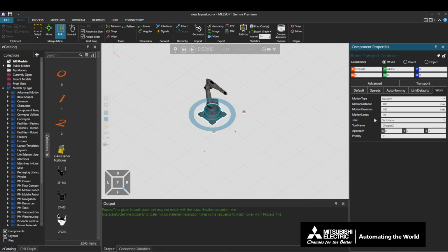Setting a keyword here requires a character string of 4 or more characters. The character string set here only needs to partially match the name of the tool to be used for it to be searched for. A tool is used by searching for a name that matches the keyword inputted in tool name by searching from the 3D world. When there are multiple tools that satisfy the conditions, the tool closest to the controller is used. If the name of the tool set does not exist, or if the tool is in an unreachable location, an error is outputted, and the robot stops moving.